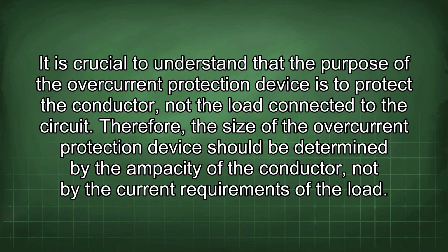It is crucial to understand that the purpose of the overcurrent protection device is to protect the conductor, not the load connected to the circuit. Therefore, the size of the overcurrent protection device should be determined by the ampacity of the conductor, not by the current requirements of the load.